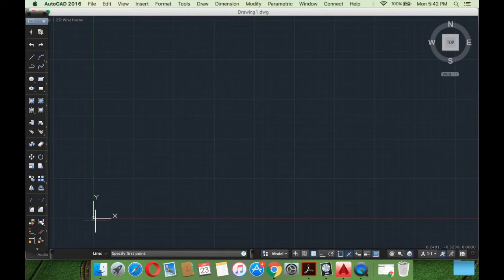So we give the first coordinate, being 0, 0, as we want to start from this particular point: x-axis 0, y-axis 0, and press enter. As you can see, we have already started drawing, and the cursor has initialized the command from 0, 0 of the coordinate system.